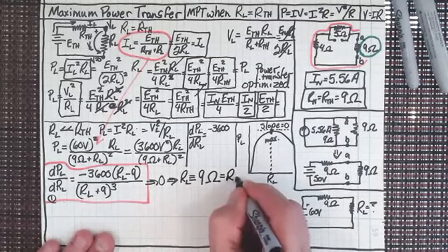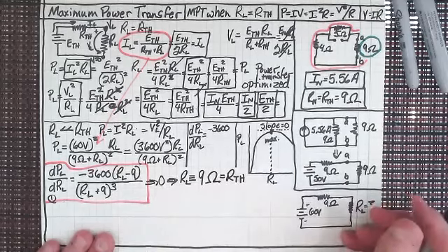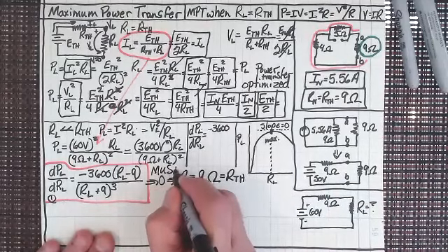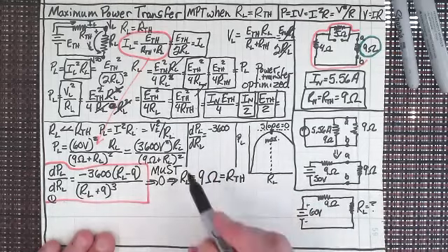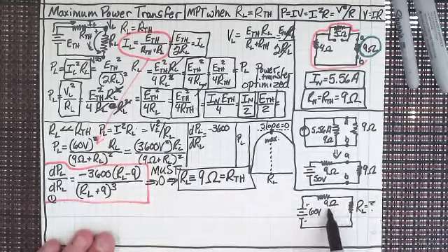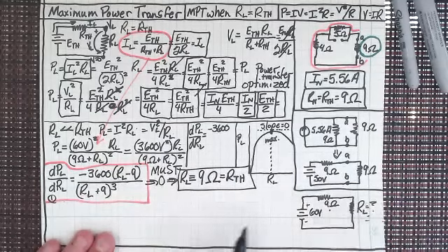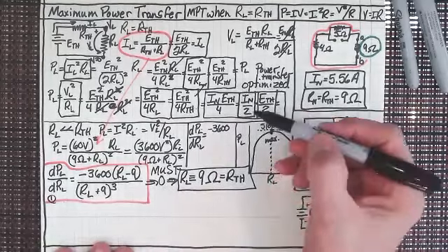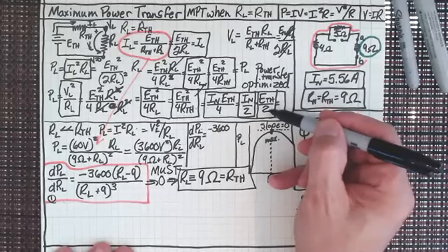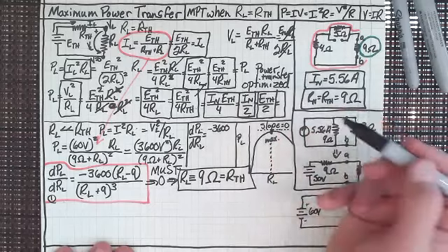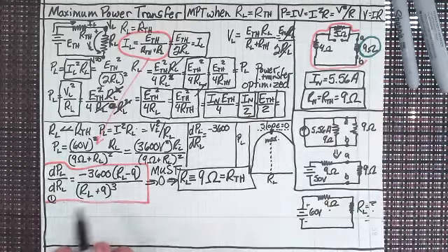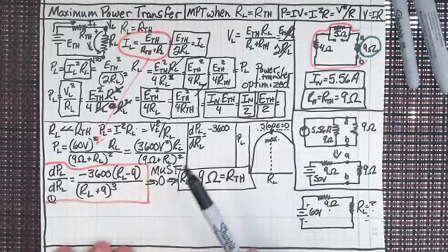which is the Thevenin's resistance. It must. Let's put that in, because this is the derivation. It must equal 9 ohms. It must equal the Thevenin's resistance to get the maximum current through there. And when you find that maximum current, it occurs when the voltage is 1/2 and the current is 1/2 of what you would consider it to be for the Thevenin's circuit. Does everyone see why maximum power transfer now? And this is good.